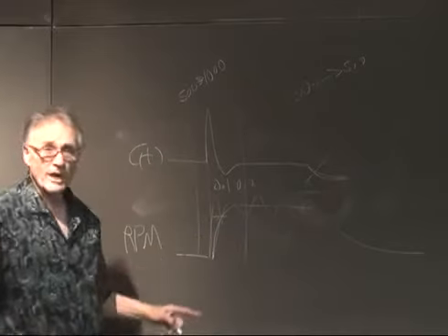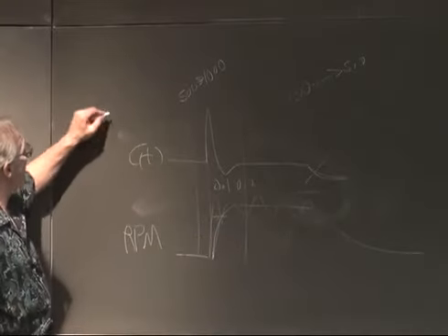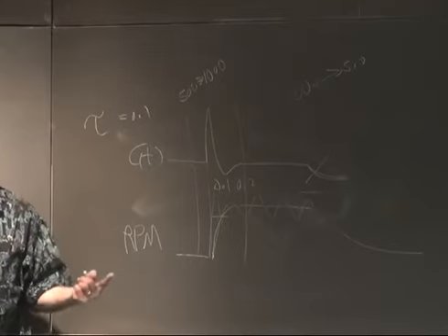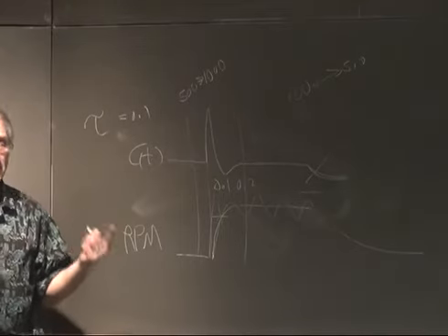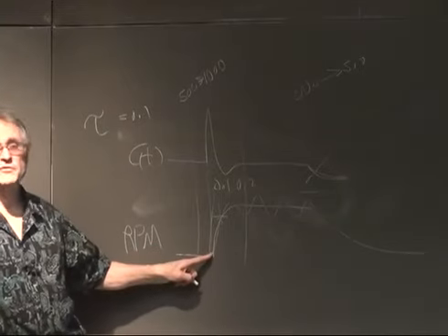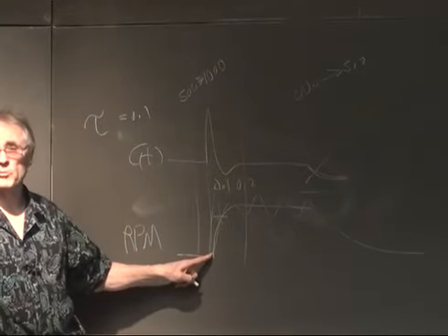Actually, yes, this should drop instantly to 0, but because of the time constant of your measuring circuit, it'll look like 1/10 of a second. And by the way, because you're using a tau of 0.1 for the low pass for the measuring circuit, you're never going to see a rise of much faster than 0.1 second.